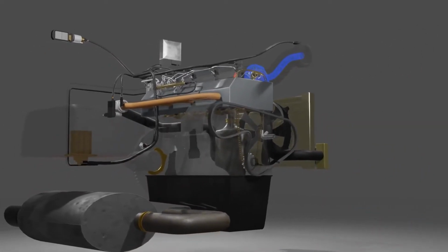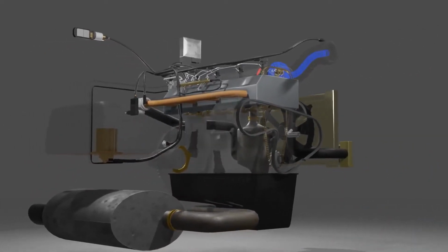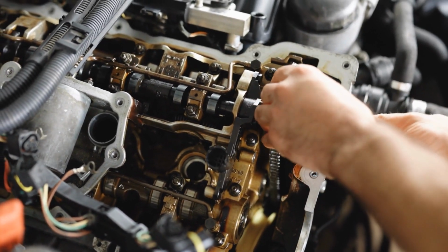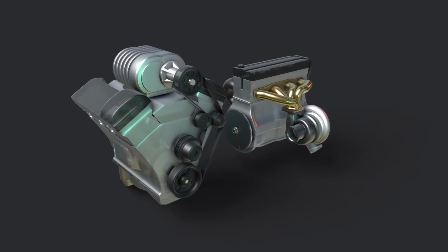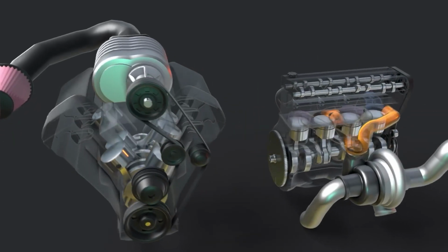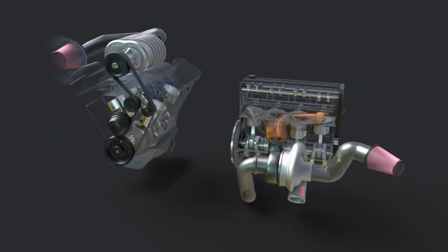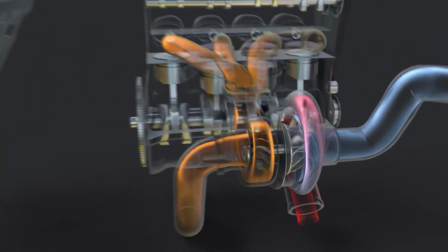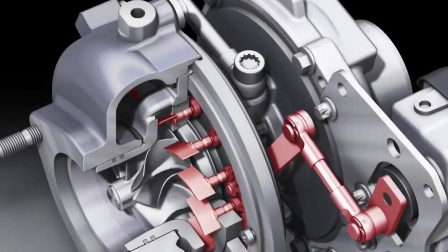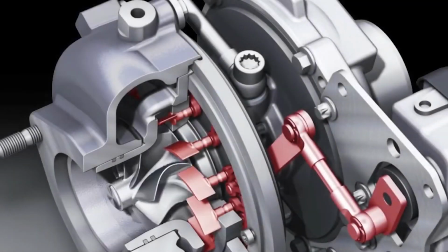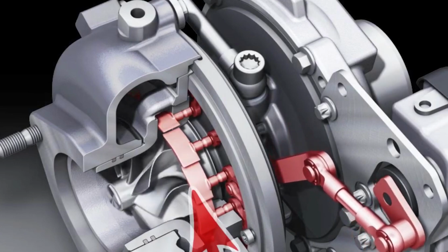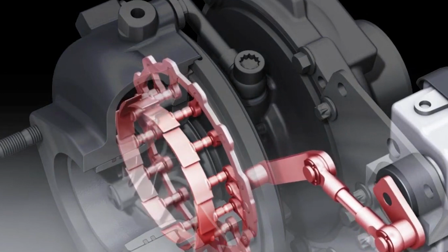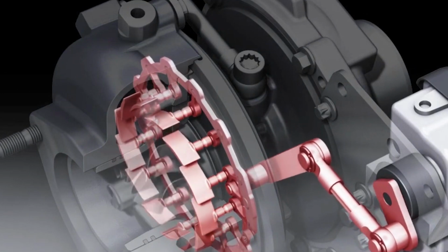The design and shape of turbine blades are critical to ensure maximum energy extraction, as they must efficiently convert the flow's kinetic energy into rotational energy for the shaft. The turbine wheel can reach rotational speeds in excess of 150,000 to 250,000 RPM, tapping the waste energy of the exhaust gas that would otherwise simply exit the engine and be lost to the atmosphere. After passing the turbine blade stage, the exhaust gases expand further in pressure and temperature before leaving the system. This sequence transforms exhaust gas energy into usable mechanical torque to operate the compressor.